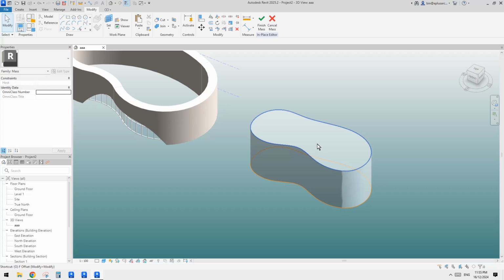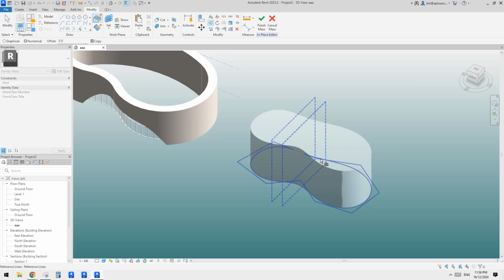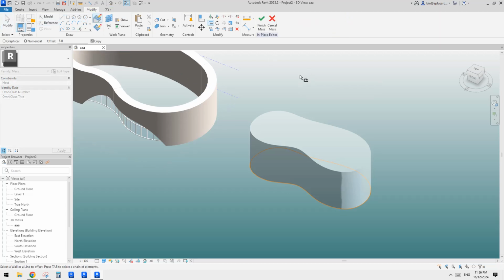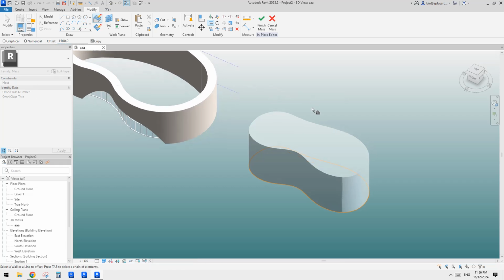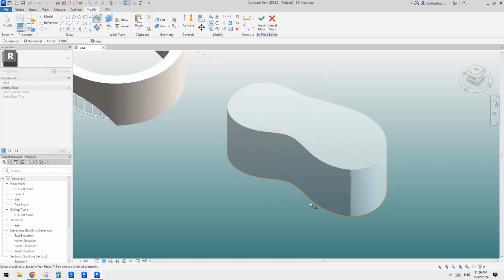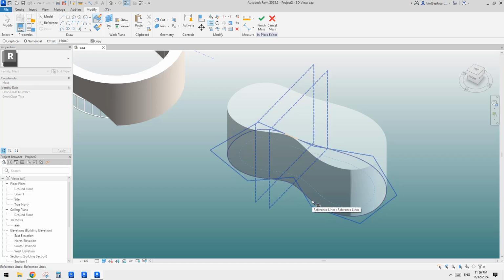We're going to use offset, OF, and then reference line. Actually, OF should work. OF with offset. Maybe I'll just make it 1.5 meters with copy ticked, move to the inside of this reference line, not outside. Okay, inside, then tab, and click.